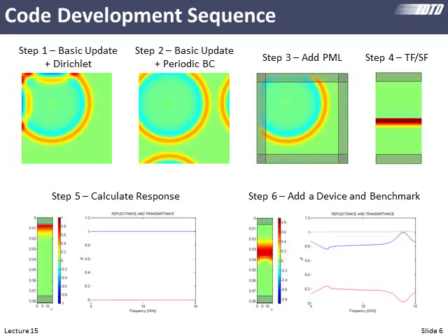But if we do that, we should see this radiated ring hit the PML regions, not reflect off of them, just get absorbed. And to the inner part of the model, it looks like that ring just kind of goes off to infinity. What we'll start talking about today is at step 4.